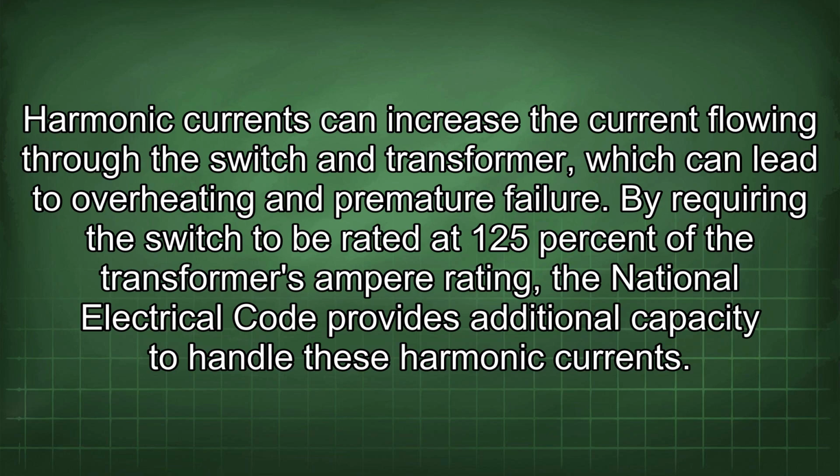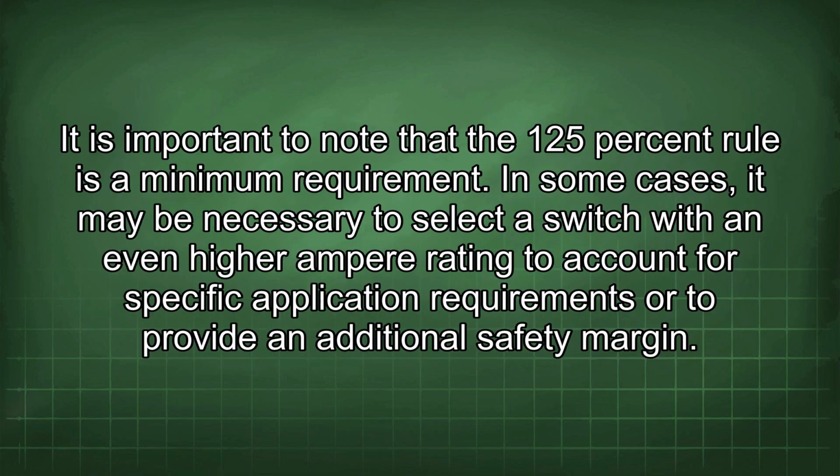By requiring the switch to be rated at 125% of the transformer's ampere rating, the National Electrical Code provides additional capacity to handle these harmonic currents. It is important to note that the 125% rule is a minimum requirement. In some cases, it may be necessary to select a switch with an even higher ampere rating to account for specific application requirements or to provide an additional safety margin.